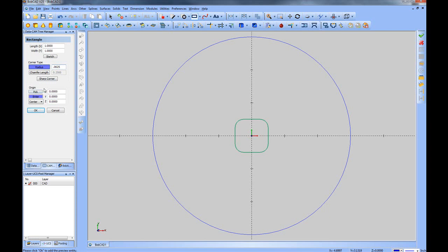And now we'll make the origin. We're going to use Enter, and what we'll do is we'll move the origin over an X 3 inches. And you'll see when you click in the Y box or in the next dialog that the rectangle moves over and shows where it's going to be placed. We'll go ahead and click OK, and that places the rectangle on the screen. That's 1 inch by 1 inch with a 0.0625 corner radius at X3 and Y0. We'll go ahead and click Cancel.